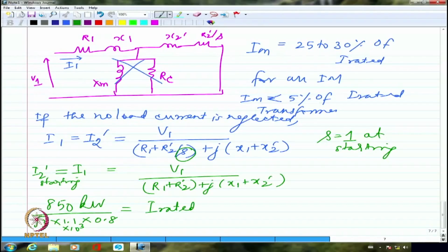This rule is there because the induction motors take heavy starting current. You will see a dip in the voltage. Normally, like a welding equipment, if you connect directly to the supply, you will see all the lights going very low. The same thing you can observe if you are starting a very large capacity induction motor, because the voltages will really sink.